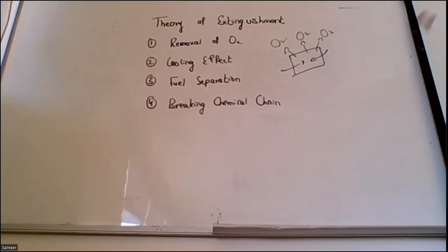Basically, what we are trying to do here is make sure that an appropriate agent is applied, and that appropriate agent has to follow some specific guidelines of NFPA 101 when we are talking about residential occupancies. And when we are talking about business occupancies and everything, NFPA 101 has some very strict guidelines. What type of furnishing you are going to use, what should be the radiant flux of the furnishings, how much radiation it should give in the environment.